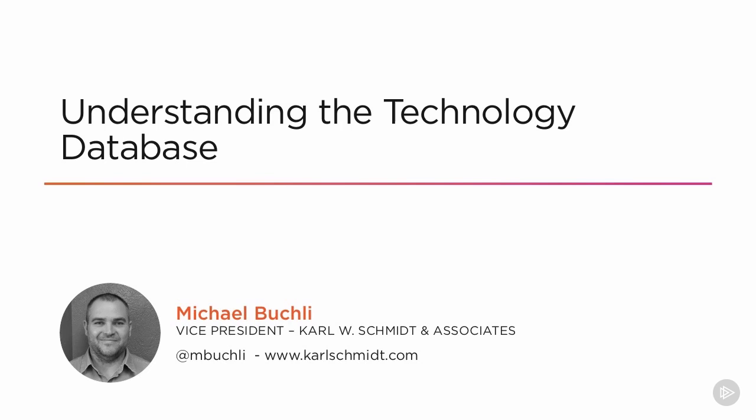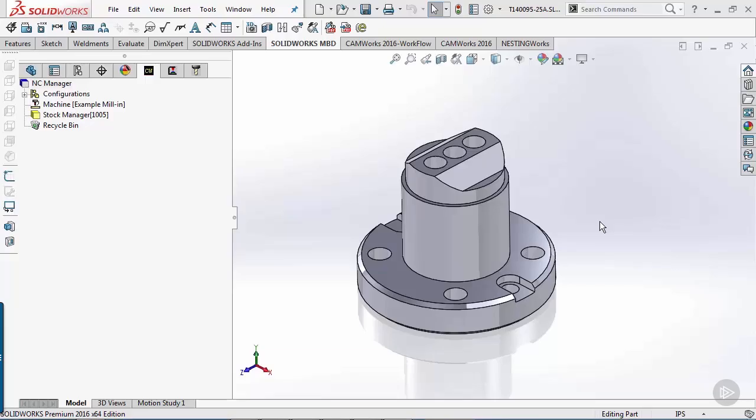And today we're going to go over the technology database and a little bit of understanding on how we're actually going to teach CAMWorks to understand how we program specifically at our shop. What we're going to do first is insert a quick little tool into this part we have here on the screen, just so you guys can see the manual way to enter a tool. And then from there we'll jump into teaching the technology database how we want to machine our parts.